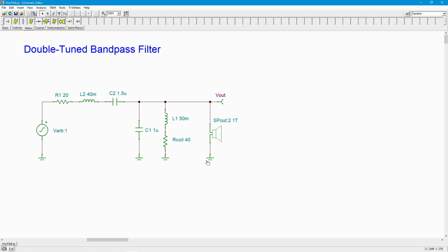And this sort of shows you what the process is going to be, right? You're going to build your circuit, you're going to simulate it, you have to run a transient analysis. Then you'll see the output waveforms, you select the waveform you want to hear, you'll play it back, listen to it, decide if it's what you want. If it's not, you go back, you tweak the circuit, rerun the transient analysis, play the output again.